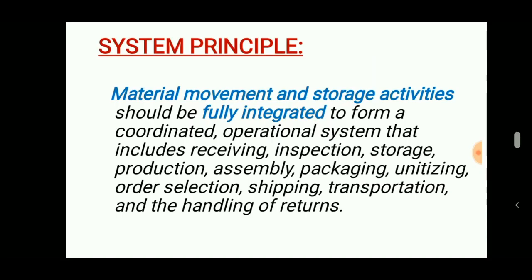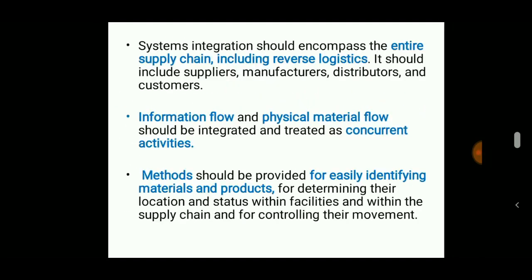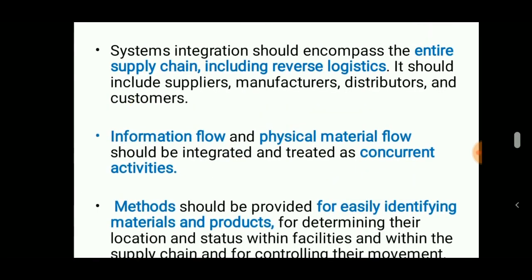Then the system principle. Material movement and storage activities should be fully integrated to form a coordinated operational system that includes receiving, inspection, storage, production, assembly, packaging, unitizing, order selection, shipping, transportation, and handling of returns. It will be a system that consists of all the tasks in a center or a single department.